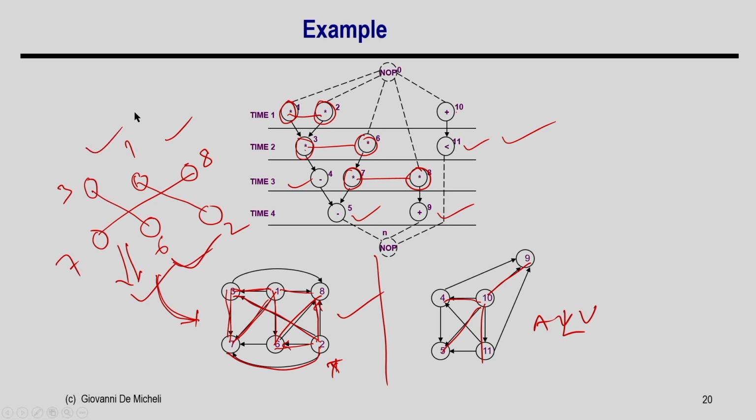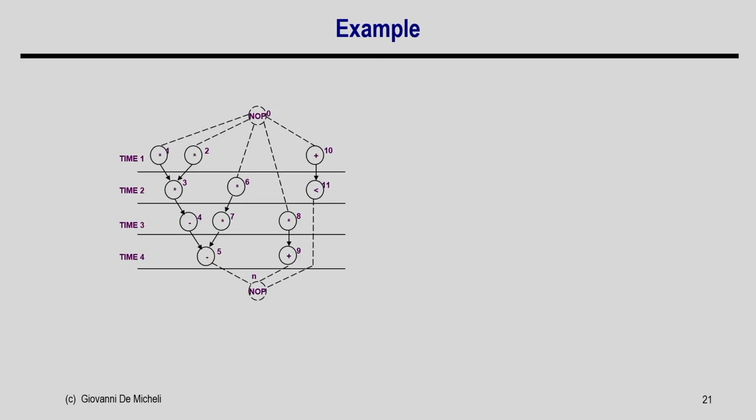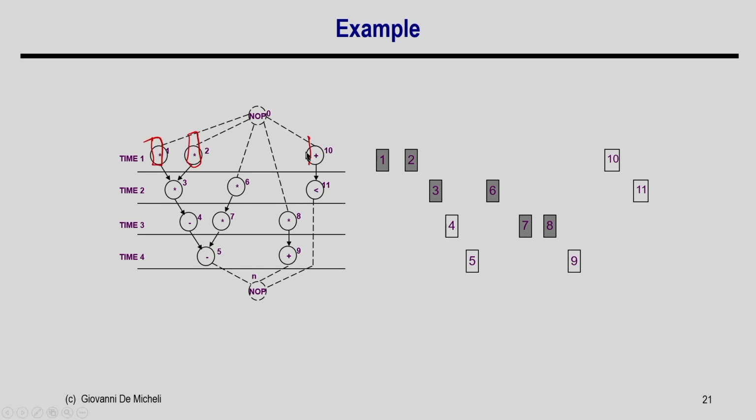And we will argue that I can map these nodes into some intervals such that whenever there is an edge between them, their intervals will overlap, and when there is no edge, their intervals will be non-overlapping. And how can I do that? That can be done easily. So, this is my schedule, and wherever the operation is scheduled, I will construct an interval for it. So, the interval of these nodes is this. I am only considering the multiplier now. So, these are the intervals.